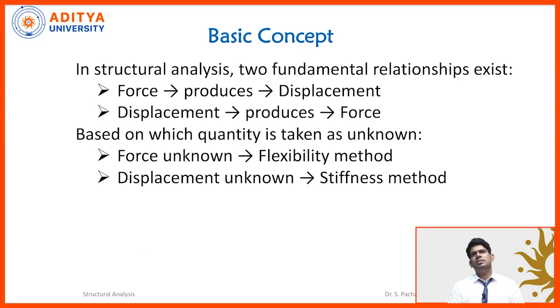In structural analysis, two fundamental relationships exist. One is that force produces displacement, and another one is that displacement produces force. Based on which quantity is taken as the unknown, these methods are categorized. If you consider forces as unknown, then automatically we go with the flexibility matrix method. If you consider displacements as unknown, then automatically we go for the stiffness matrix method.